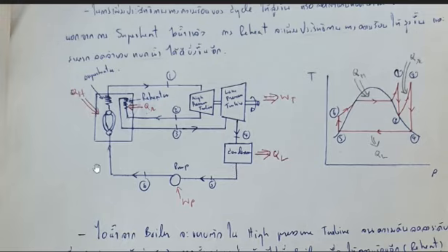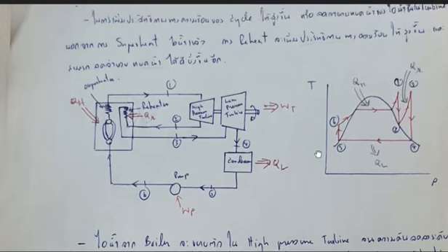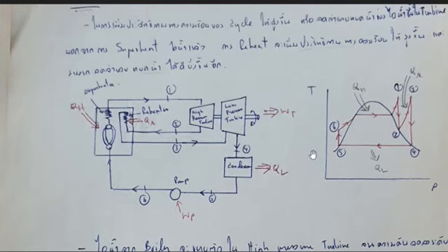And then the steam will go through the condenser to be converted to water again. If we look at this graph, the temperature versus the entropy, you can see that from the water at state 5, if we pump to the boiler pressure, this is the pressure line.